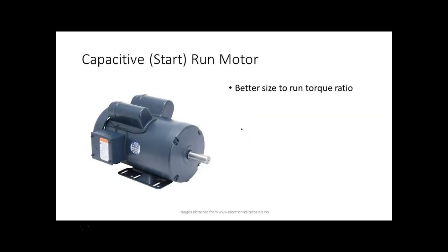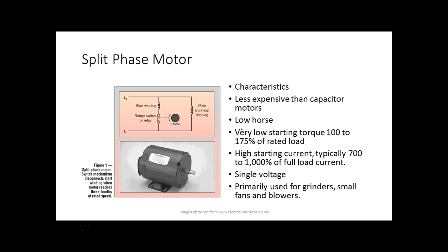Showed y'all that guy, right? Then we have what we call a split phase motor, less expensive than capacitor motors. Low horsepower, very low starting torque, 100 to 175% of rated load. High starting current, 700 to 1,000% of full load current.